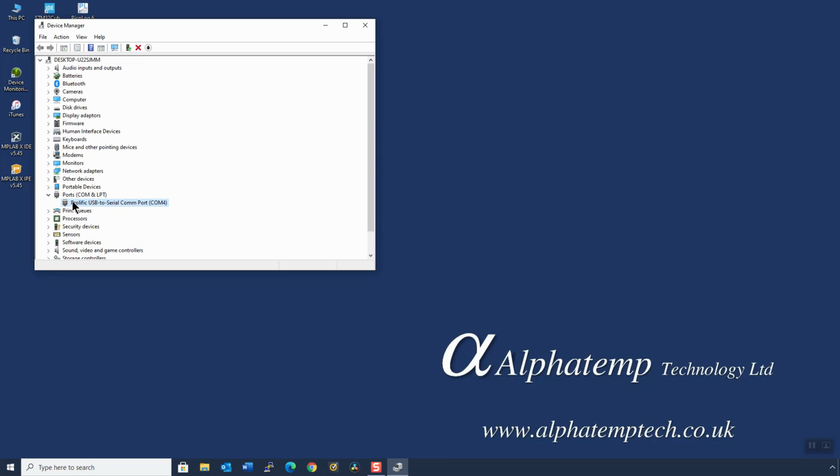If it doesn't, then there's a number of things that we can try out, and I'll cover this in another video. Now, if you do find that the actual COM port number has appeared, but you're still having an issue, what you might try to do is to unplug the USB adapter and then wait for a few seconds and then plug it in again and exit and restart the software, and that might sometimes solve the problem.